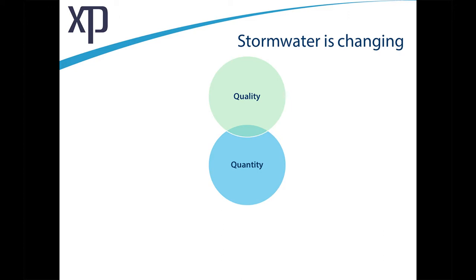We're looking at stormwater management that tries to mimic natural drainage by retaining pollutants on site and treating the water, slowing it down in a similar way to the environment before we develop and pave these surfaces. So now we also want our stormwater solutions to be attractive and actually contribute to the amenity value of the site. Rather than just being a take on the land, we can actually start to think of these stormwater solutions as adding value.